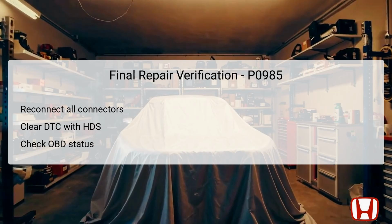Start the engine with the shift lever in Park, P, waiting for at least 1 second, then shift it to neutral, N, and again wait for 1 second. Finally, monitor the OBD status for DTC P0985 in the HDS. If the status indicates passed, the troubleshooting is complete. However, if it shows failed or not completed, further investigation is required.